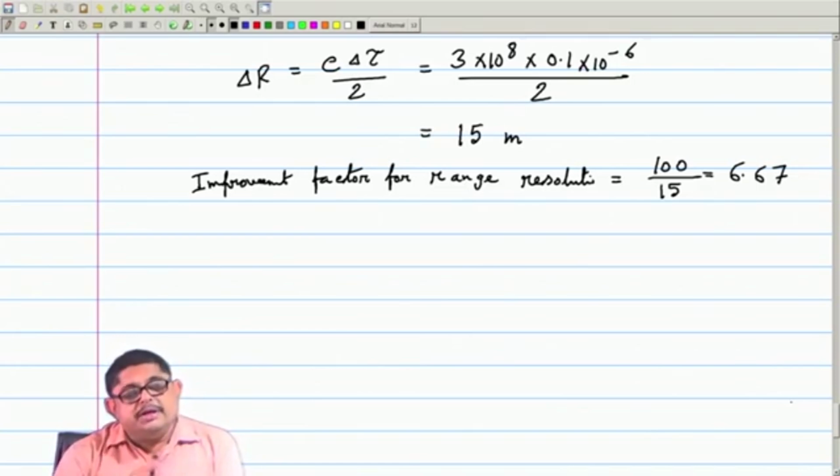Actually, you see that by giving the phase, in the phase there is an exponential variation with time. Actually, you are making a large pulse behave as a short pulse, so that its ambiguity function is narrowed and its resolution is improving, but you are not losing the benefit of the large pulse, because a large pulse can carry a large amount of power.